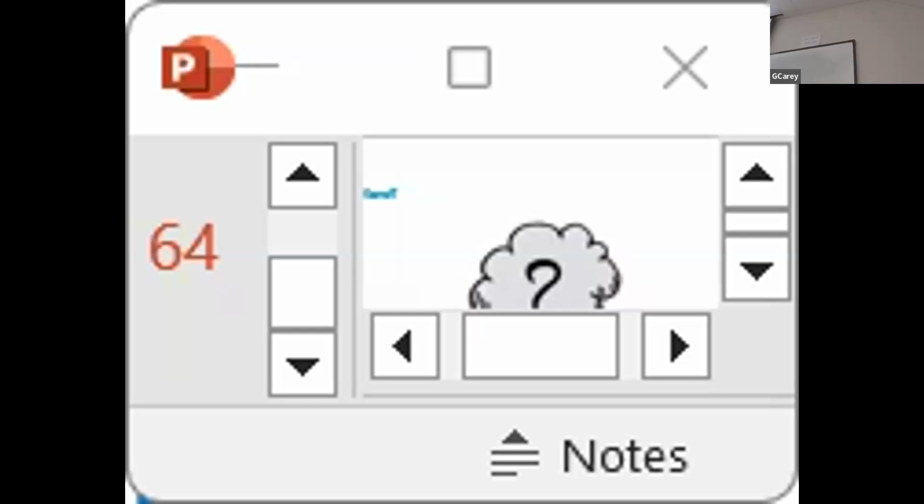And again, that's typically when you're going into that software selection, and they'll say, hey, variable speed, okay, what's your control head? And they'll type in 15 feet, 22 feet, whatever that number is, usually a percentage of maximum. So that when it builds that system curve, which it will do automatically in the software, that's your starting point. So that pump's always going to develop that minimum pressure differential head.